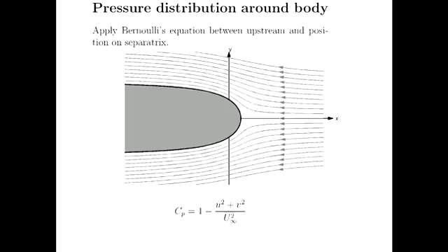So we could do it numerically, all right? If you did it with MATLAB, you don't really have to solve anything algebraically. We can just substitute our known expressions for u and v into that, or just evaluate them at given positions, and we'll be able to calculate that pressure coefficient.